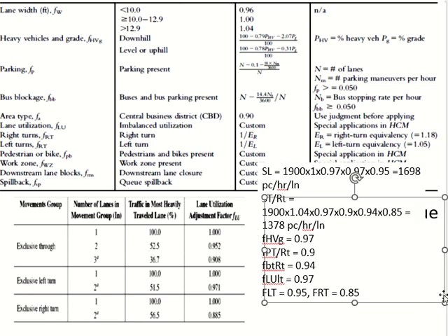Okay, so the only thing you need to take care about is the applicability of the factors. Which factor will apply where? Two factors without any exception will apply everywhere. And these two factors are which ones? Lane width and heavy vehicle and gradient. Okay, clear?